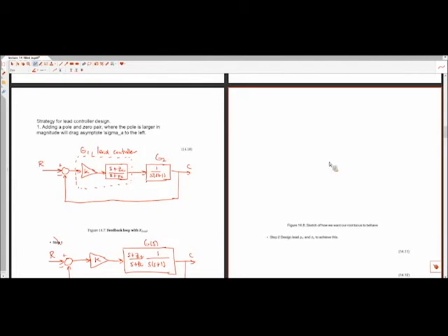So what we're attempting to do, in a really brief sketch, is this: we have the poles of our plant. Those don't go away. Those will always be there. We can't do anything about those. Those are fixed. What we're doing is adding a compensator so that it's going to put a portion of the root locus between here and here, by dragging the asymptote to the left.